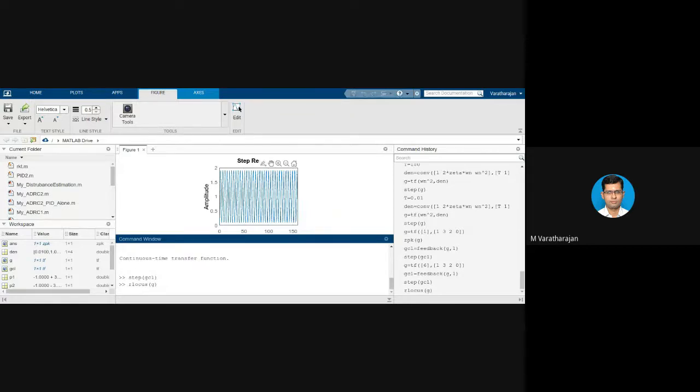If you plot root locus of G, it will show a graph in which each and every point corresponds to a value of K. Root locus, by definition, is the path traced by the closed loop poles of the system when any one of the loop parameters of the system varies. Usually for design, we consider K. Okay, so this graph is for K varying from 0 to infinity. Okay, actually, this will not be infinity, K varying from 0 to some high value, because infinity means you require an infinite graph.